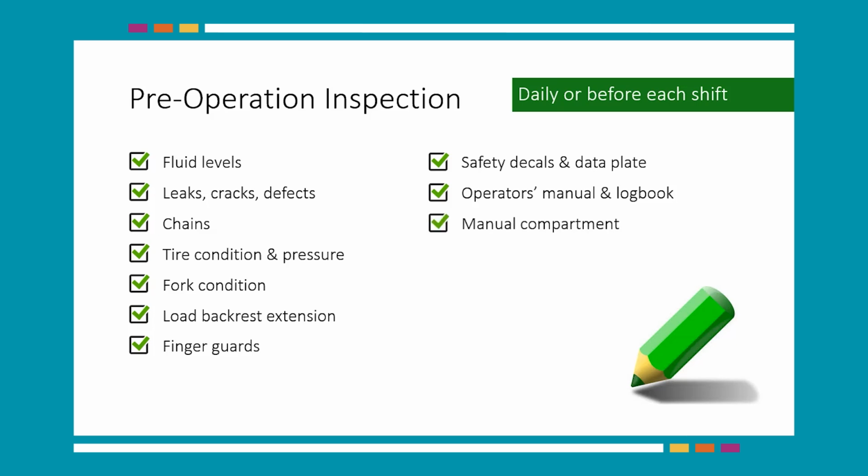Ensure the operator's manual compartment is clean of any debris. Test all functional safety devices, such as seat belts and horns. Check the brakes, steering controls, and other operational items for proper function.